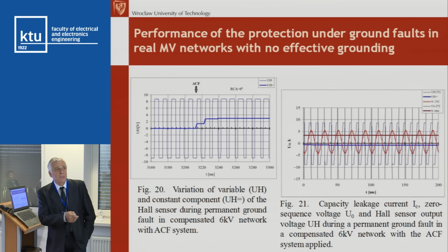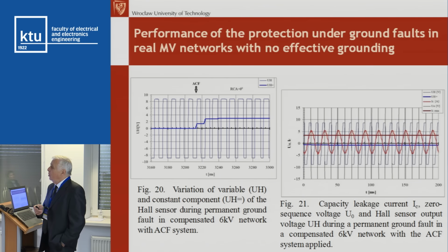These are like steps in the current. This is not forced exactly the same. Probably the loop resistance is being changed. Therefore, once it is increased a little bit and another time by about 20 amps. And here is the indication, since we located this protection not only on the faulted line but also on the healthy line, to compare what's going on on the healthy line.